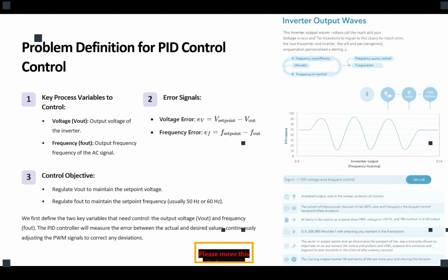Okay, and we said we are going to talk about that in detail after the midterm, but in order for you to have an idea: when we want to control active power, we have to control the phase of the voltage. By controlling the phase of the voltage, we could control the injection or consumption of active power.